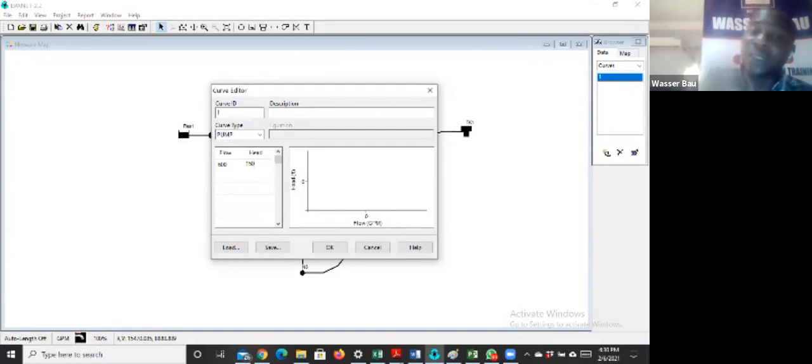But we know that losses in a pipe network are a function of 3 parameters I told us yesterday. One is the geodetic difference, which is a head that needs to be overcome. The next one is the frictional factor in the pipe. The friction in the pipe is another thing that needs to be overcome. And the last one, which is not often mentioned, is the velocity of flow. There's a friction due to velocity of flow. There's a friction due to pipe body, which is a K factor due to pipe roughness. And then there's friction due to overcoming gravity.